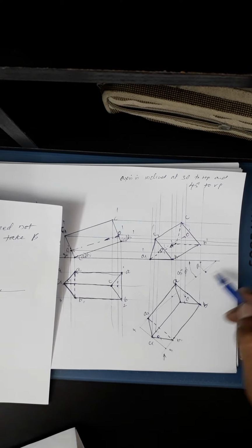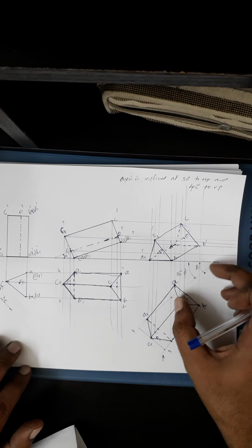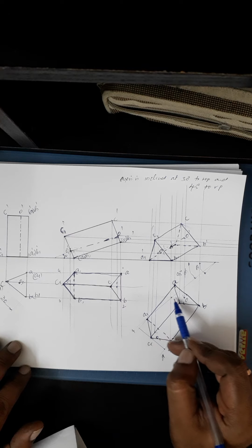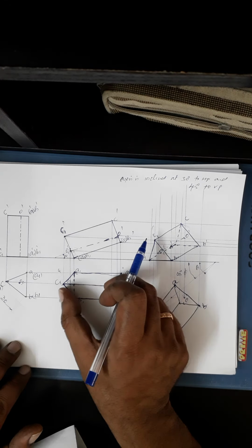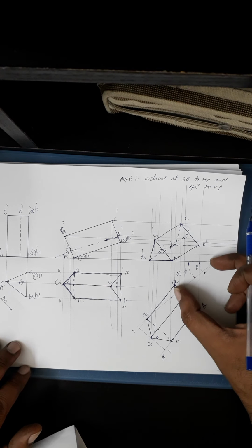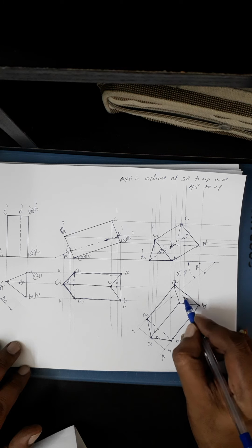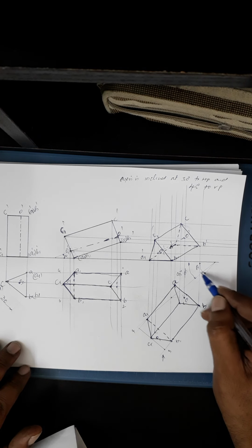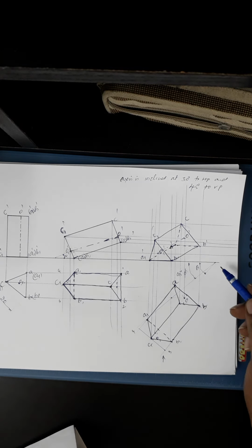See, same thing here. I have drawn a line with a true inclination of 45 degrees, taken a true length of 60 on this, and drawn a locus parallel to the XY line. Then, taking this apparent length, which is less than this length, I have drawn an arc, so that it cuts here. The line joining this point to this point will give you the beta angle. So this is beta, which is more than this angle of 45 degrees. This is the procedure of finding beta.